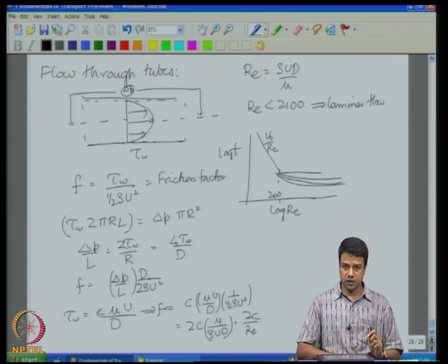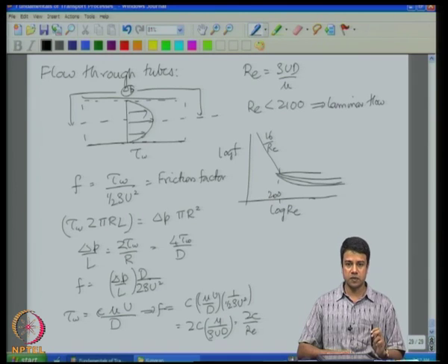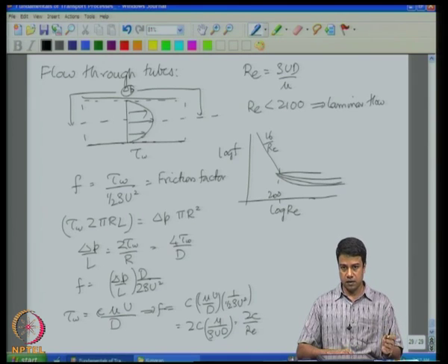For example, the Schmidt number is the ratio of momentum diffusion and mass diffusion. The Prandtl number is the ratio of momentum diffusion and thermal diffusion. In the case of natural convection, you have dimensionless groups that are once again a ratio of convection and diffusion, except that convection is caused due to buoyancy forces.